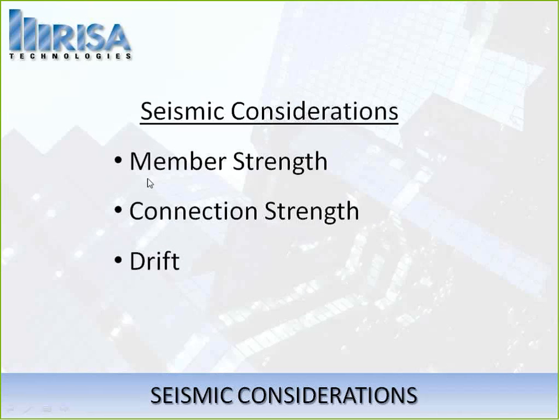As you'll see, we'll actually design your members and give you full code checks based off all the seismic provisions. With regard to the connections, we currently don't have seismic connection design in the program, although that is on its way. And we're going to have connection strengths reported in the current version of RISA-3D. Now, as for drift, we haven't made any changes in this release to the way that we report drift, but we will eventually be making some improvements to that as well in a future release.